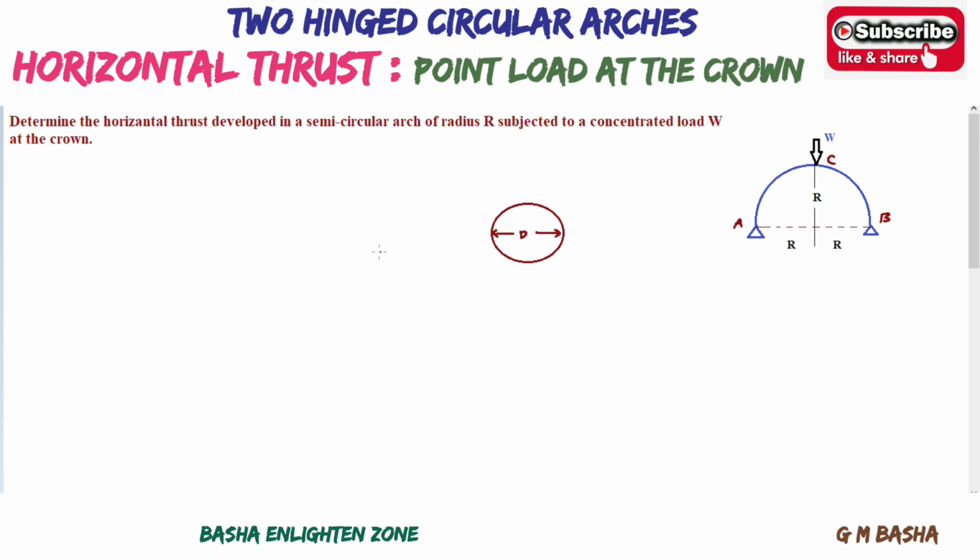First, find the vertical reactions at A and B. It is the general procedure: reaction at A and reaction at B. I already explained the conditions. Resolve, sigma MA equals 0. Take clockwise moments on one side and anti-clockwise moments on the other side. Force RB into distance 2R, which is anti-clockwise. Similarly, force W into distance R. If you cancel this, you will get RB equal to W by 2.